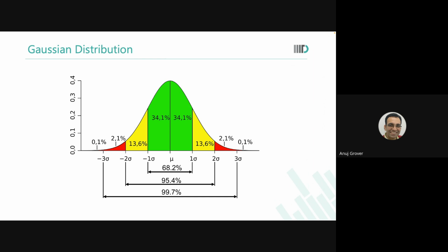चल जाता है. So now do you realize that why is mismatch a much more critical challenge in memory design than it is in analog design? We already talked about the fact that our devices are not as huge as they are in analog circuits. Now we are talking about the sigma extent that we need to qualify. Now, I'm not saying that PLL teams would qualify only plus minus 3 sigma. They would also qualify more than this. But even with plus minus 3 sigma, they can at least pass. You can't even have one memory working if you do plus minus 3 sigma. They will have some respectable yield. आपका तो zero yield आएगा.